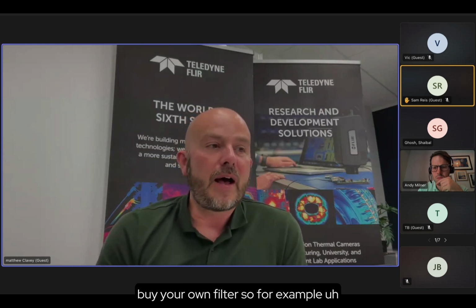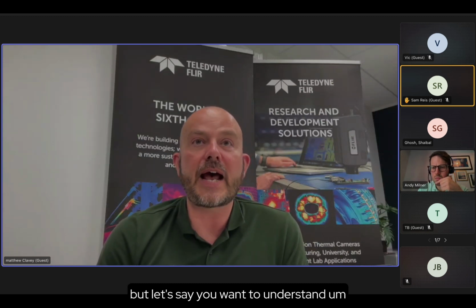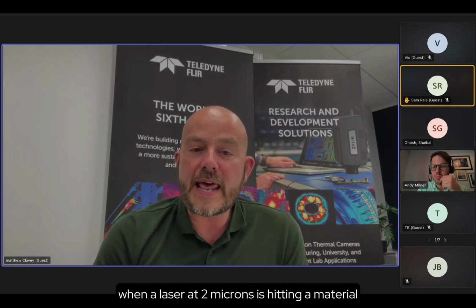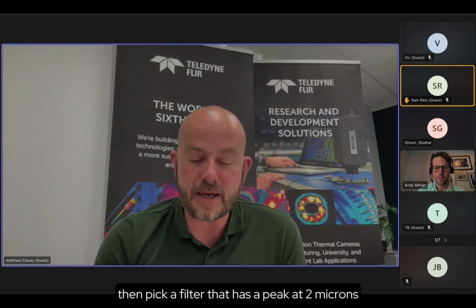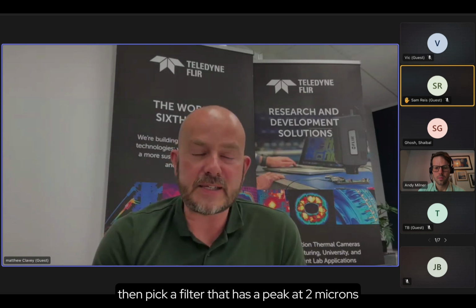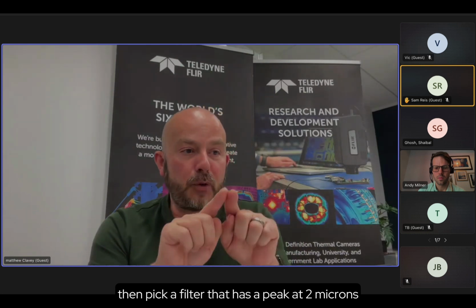For example, a cooled camera may have a wavelength of 1 to 5 micron, but let's say you want to understand what's happening when a laser at 2 microns is hitting a material, and you very specifically need to look at the laser. It could be that with a 1 to 5 camera, it's slightly too wide to see the laser. So we would help you pick a filter that has a peak at 2 microns, but also a width.